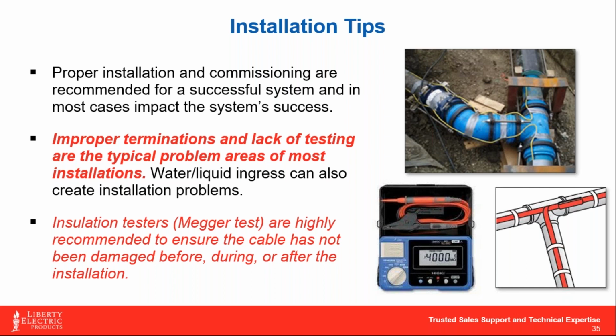So really when it comes down to it, specifiers, I would strongly recommend for you folks that you either integrate startup and commissioning into the spec, an evaluation by either the manufacturer's rep, or the installers have to submit Megger readings, resistance readings, before, during, and after on the project, to ensure that the cables were installed correctly and that they're in proper working condition, to close out that portion of it.